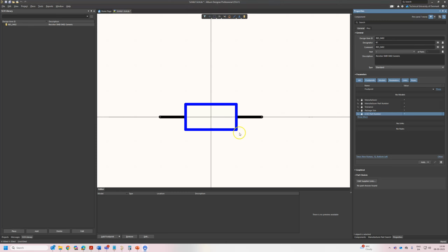But in case you want to use this in your schematic and you have a specific type of resistor with a specific tolerance and specific application, you can easily write all these parameters here even using a generic resistor. So they are really useful to have, and you can get those numbers from your supplier. I will show you how.